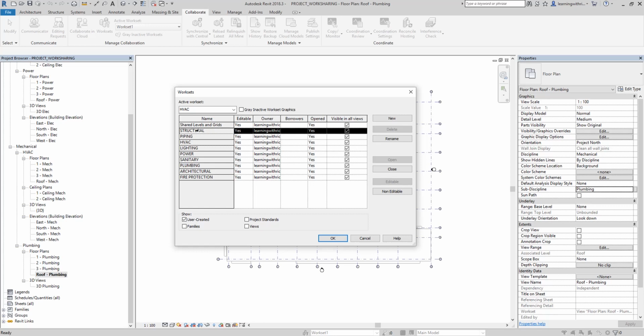Okay, well, it depends on the project, but in most of the projects that I've worked on before, we do not put an ownership on the work set, so that all team members will be able to use the work set that you have created. But it is case by case. So if you really don't want your elements to be modified by other team members, then you can own the work set. But in most projects that I have worked on, it is not the case.